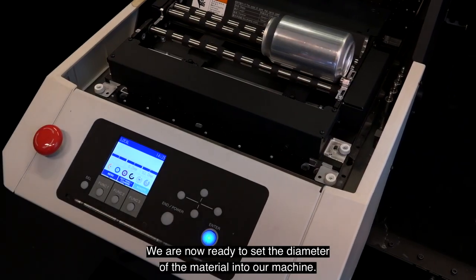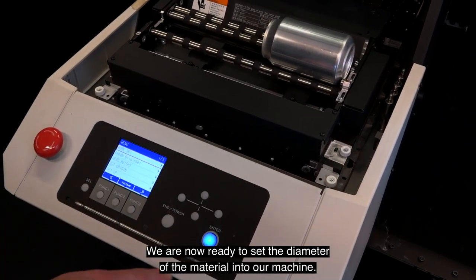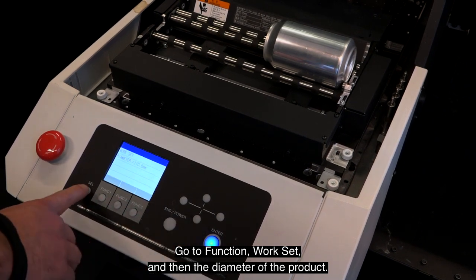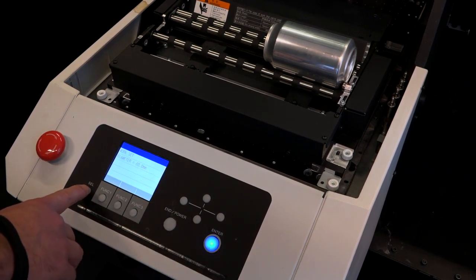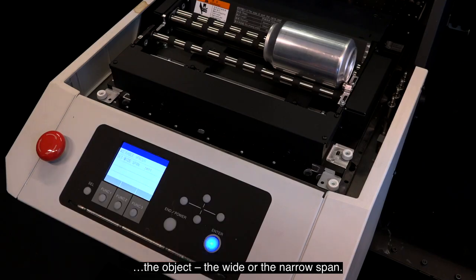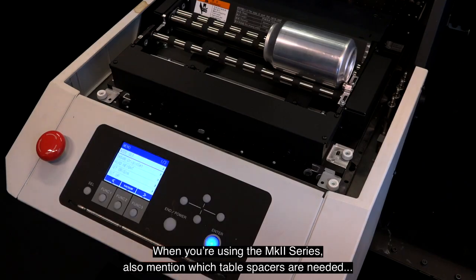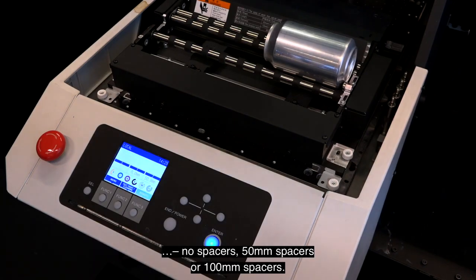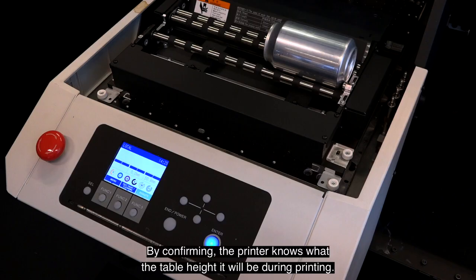Okay, we're now ready to set the diameter of the material in our machine. We go to Function, Work Set, and then the diameter of the product. Confirm with Enter, and a display will indicate which span you need to place the object, the wide or the narrow span. When using the MkII series, also mention which table spacers are needed: no spacers, the 50mm spacers or the 100mm spacers. By confirming, the printer knows what table height it will be during printing.